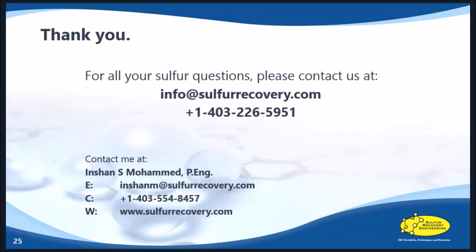We have one question that came in. What are the temperature change step guidelines to best protect refractory? Definitely a great question. Like I said, I'm going to be answering this verbally. Typically, we're talking about a step change of 50 degrees Celsius per hour, maximum 100 degrees Celsius. You want to definitely check with your refractory vendor with respect to specifics to yours, but typically it's around that 50 Celsius, 100 degrees Fahrenheit per hour in order to protect that.